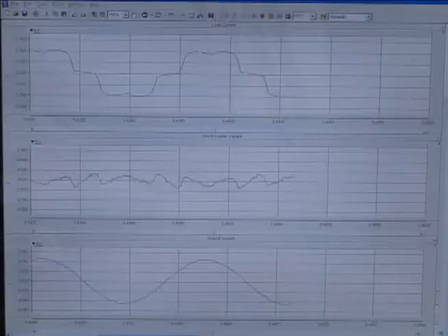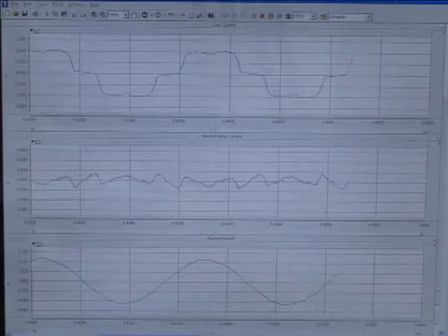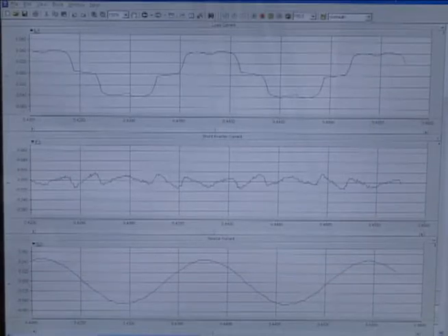Direct connection up to 690 volts for industrial filters. Automatic derating function for applications where the switch room temperature is too high. Easy-to-use graphical user interface incorporating a variety of network measurements and remote communication possibilities. Thanks to these features.